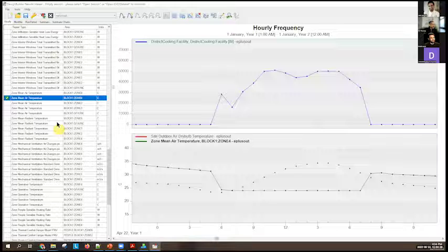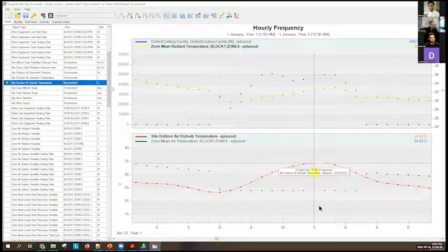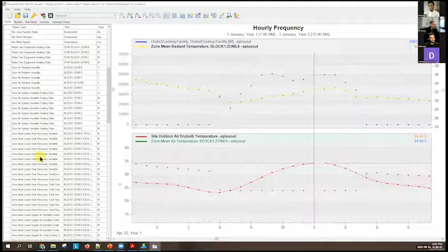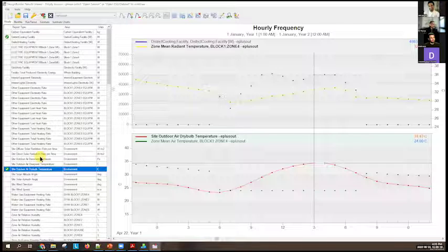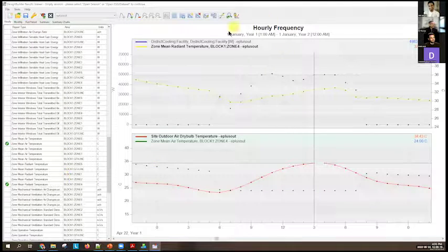But the air temperature is not sufficient. If you look at the radiant temperature, that is what you perceive. And you can see here that the temperature is quite a bit higher than 24. The thermometer says it's 24 degrees centigrade, but because this is a very poor fabric, maybe 24 degrees air temperature, but what people are feeling is 34 degrees centigrade. And typically we use a number somewhere in between, and that's really what, sorry, that's outdoor temperatures. Outdoor mean air, sorry, radiant temperature.